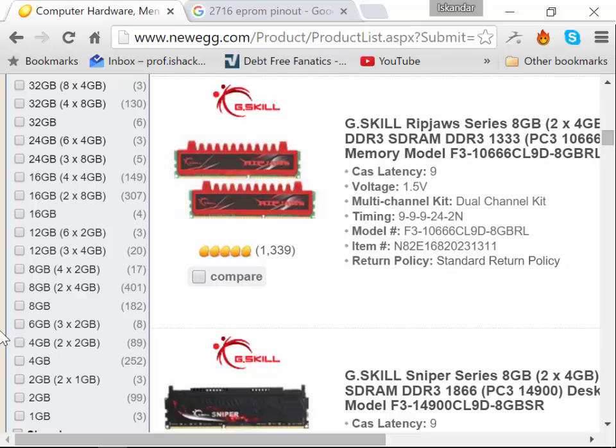The most common two you're going to see are static and dynamic. Static RAM uses flip-flops. When you talk about computers, like in a basic digital class, you covered JK, D, and SR flip-flops. So you set and clear a memory location. Each flip-flop requires 4 to 6 transistor cells, which means static RAM is very large in size, because every bit requires 4 transistors.